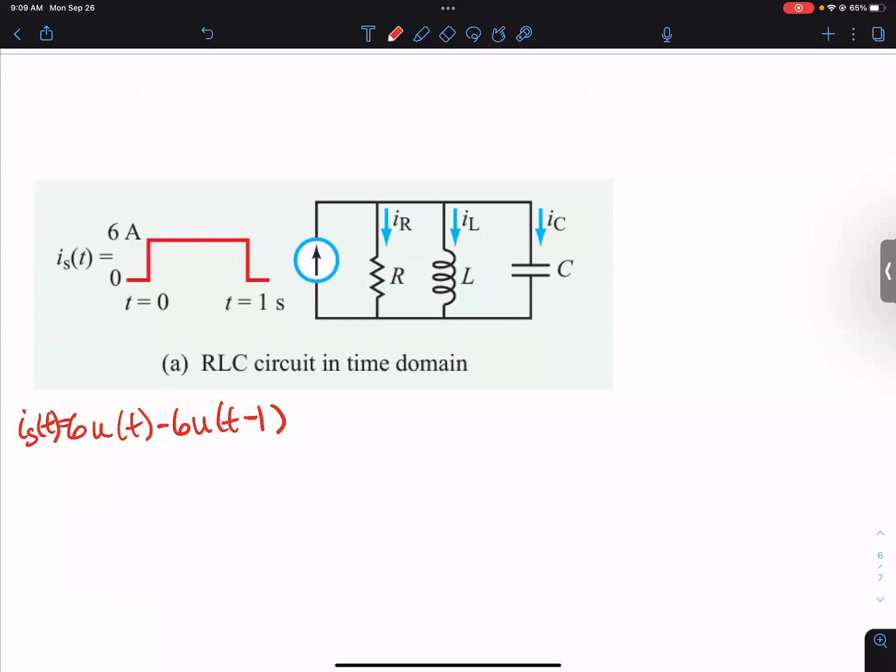All right, so what next? So first we need to write it in the time domain. What is the input signal? Would you replace the components, the inductor and capacitor, with the parallel forms? So yeah, I think that would be an easier one in this case, to do the parallel forms, because then all of them are in parallel. And then I could use node voltage, and it's just a node voltage out of each of those branches. So that would be my choice too.